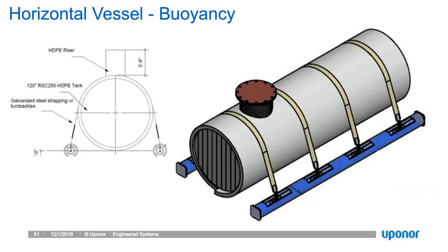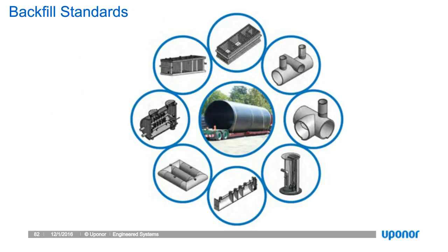So before we get into a couple project profiles quickly, I just want to discuss backfill standards. Buried pipe structure design, these are flexible conduit structures that are basically soil structure interaction systems that rely on high-quality backfill compacted to 90% modified Proctor in uniform lifts on both sides.